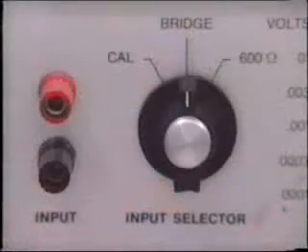Whenever you're using dB scales or dB measuring instruments, always check the reference values, usually 600 ohm and 1 milliwatt. This is important because you may have to apply correction factors based on this information. An example of this is shown in your workbook.